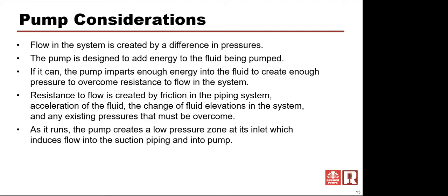Of course, in a system, if you change the fluid elevations from where you're pumping from and pumping to, that is a resistance to flow. And any existing pressures in that system, such as a pressurized header that I was talking about, a 50 PSI pressurized header, you have to have enough pressure on the pump side to be able to overcome that resistance.